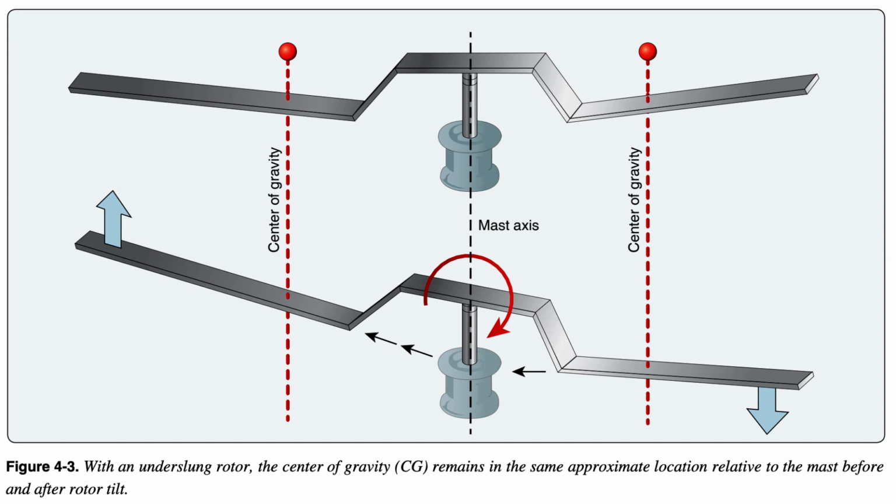The underslung rotor system mitigates the lead/lag forces by mounting the blades slightly lower than the usual plane of rotation, so the lead/lag forces are minimized. As the blades cone upward, the center of pressures of the blades are almost in the same plane as the hub. Whatever stresses are remaining bend the blades for compliance.